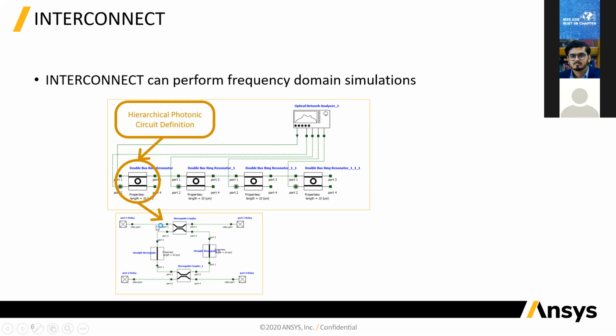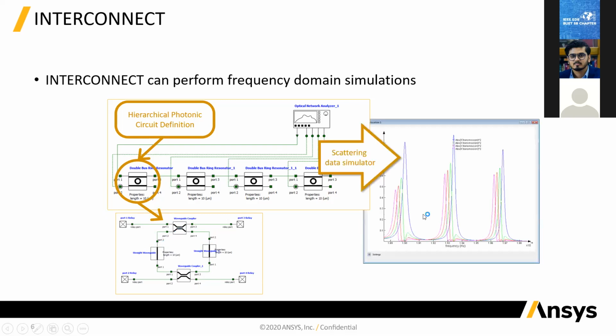And then you have the waveguides inside to create the ring. So these four components create a single ring resonator. Then you use a compound that includes everything inside it. And then on the top level, you can simply have these compounds build your entire circuit. And the output would be, say, the frequency spectrum for your device.